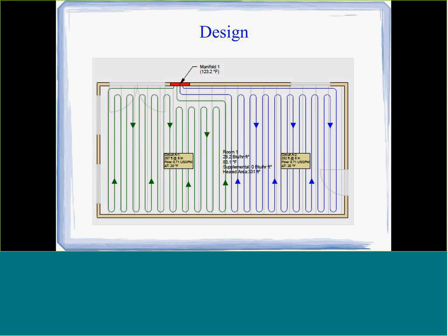Typically something like this, you're going to be looking somewhere in the neighborhood of 20, 25 BTUs per square foot, and we can calculate the boiler load from that. And also, by knowing what our load is, we can also calculate the pump size too.